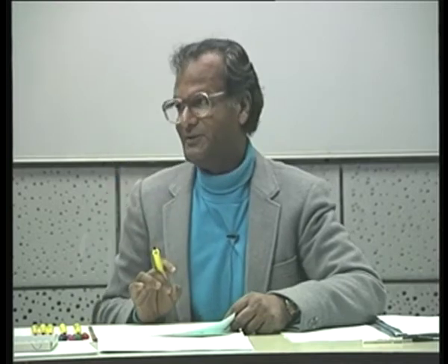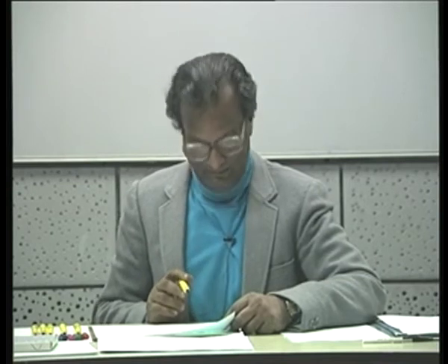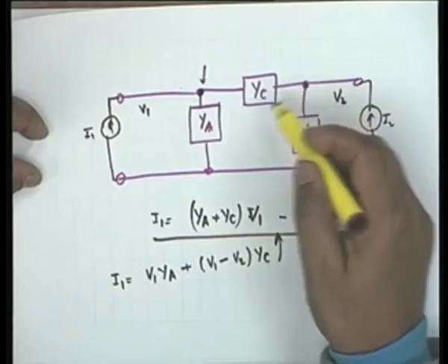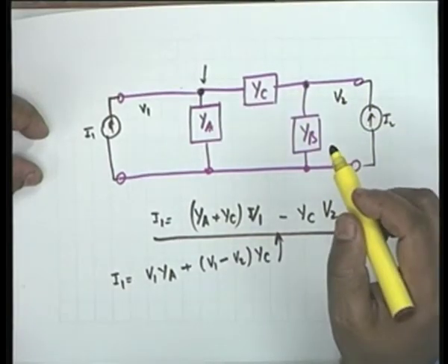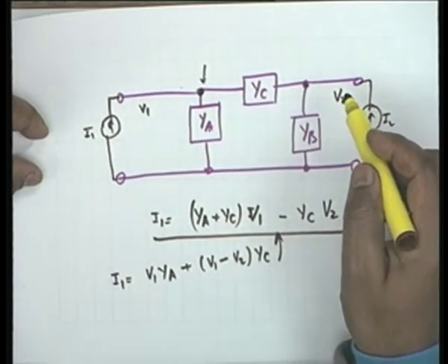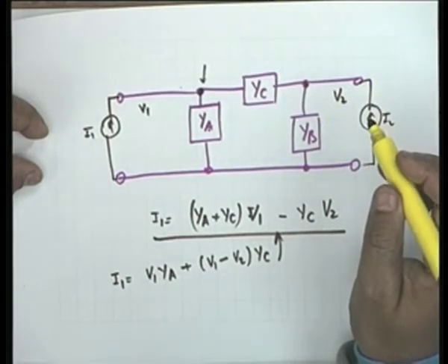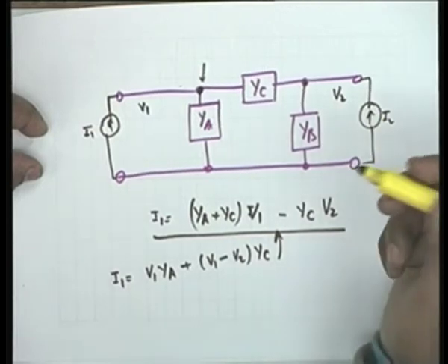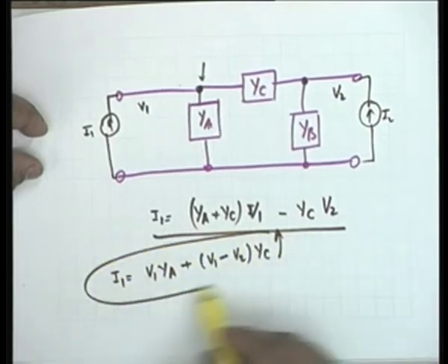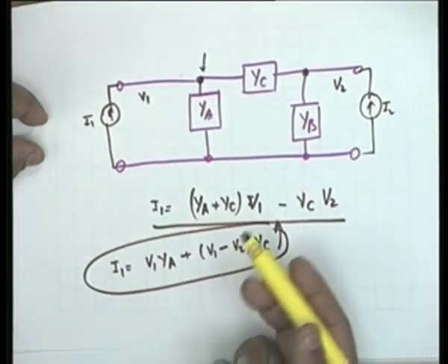It's always better to go to the roots. For instance, the mutual admittance between voltages V1 and V2 is what gives us the second term, YC V2, because it's connected between those two nodes. With respect to the first node, that is why we are taking it up to the second node and relating it to the voltage V2, because it's connected between V1 and V2. We had no alternative. This is dictated by KCL. As I said, I am writing KCL here, which is exactly the same as this. We have no choice. This is how it will come.